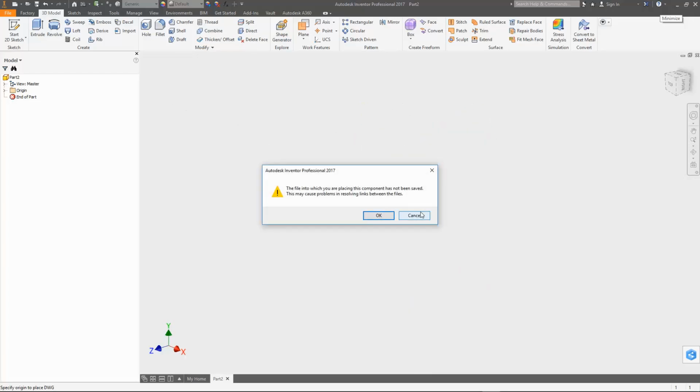No worries about this message. It only tells you that the inserting of an AutoCAD DWG creates an associative DWG underlay. This is exactly what we want. If the DWG geometry is changed, the Inventor IPT should also be updated.